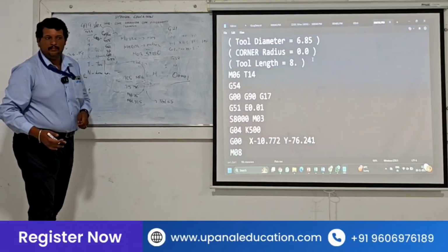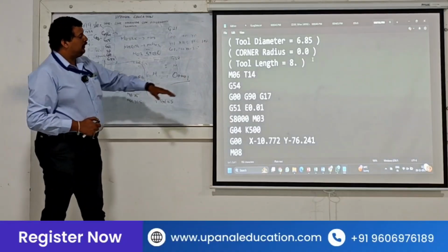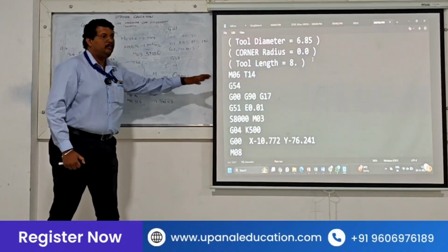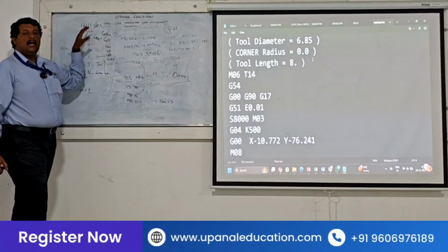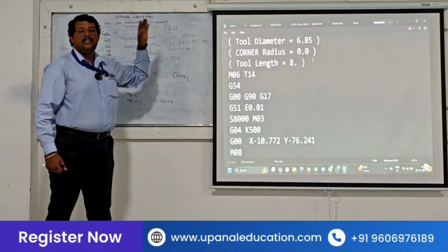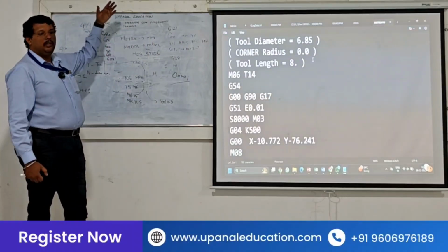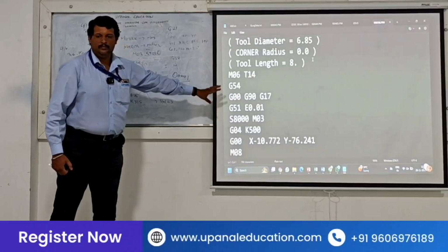Whenever these works come again, instead of putting G54, if I am doing the second job, I will put G55, or I will put G56. So it will take that machine center, and if I am going back to the old work, the first work, I will again put G54.